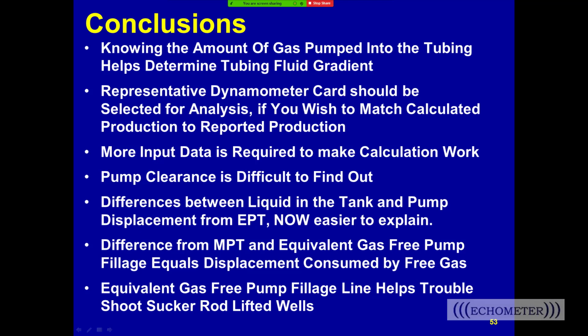And so for Kuwait, their wells are very shallow, and they're very viscous 10 API gravity crude. And in a lot of cases, their temperature is changing because they're trying to do a thermal flood, so they're trying to heat the oil up, and that drops the viscosity. But if they don't maintain the heat, then the temperature of the earth cools off back to normal temperature, and the oil becomes much more viscous. So it's an issue of not just the gravity of the crude, but also the temperature. So the temperature can also cause a problem.